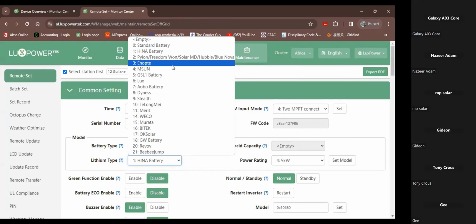If we haven't listed it, it means we haven't tested it. But if your supplier tells you they have, you're more than welcome to select the lithium function and to use whichever protocol they tell you. But if you don't have satisfactory results, meaning that your charge current limit is limited, or there are limitations on the discharge current limit, or you have delays in switching time, it simply means that it is BMS related. And then you might have to go to a lead acid setting.